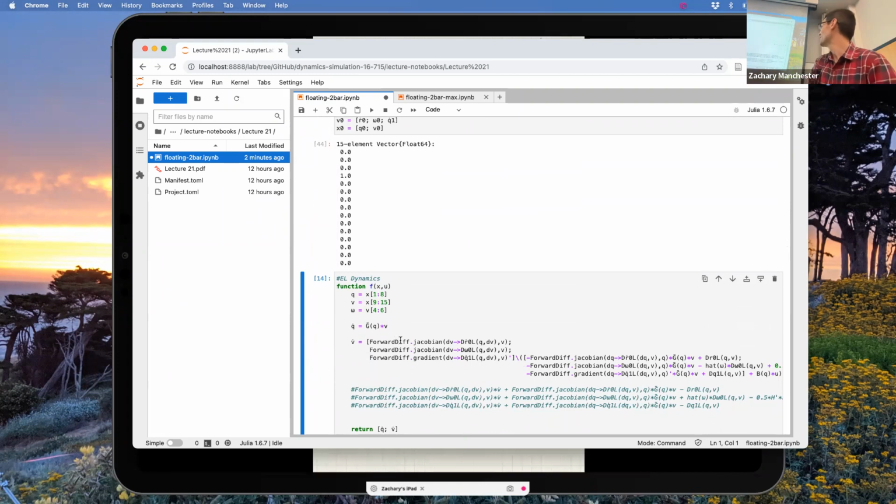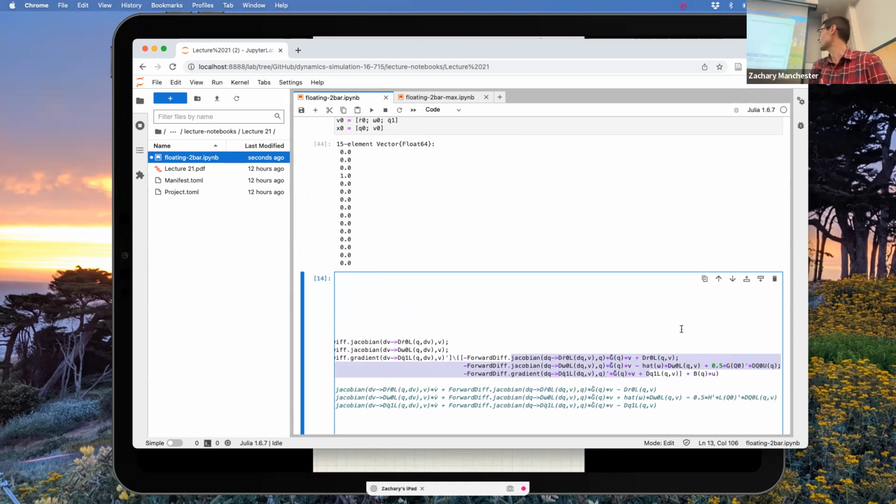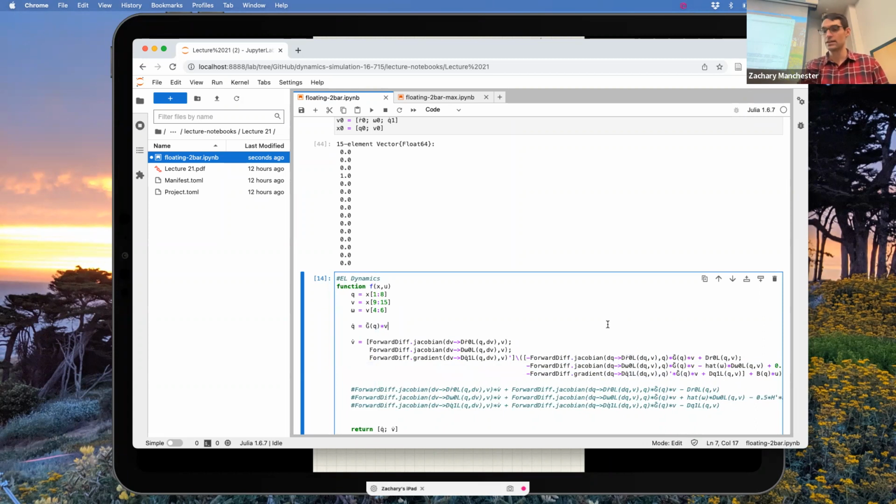So this is messy. But remember, basically what I had was pieces that were separated out for the position, the quaternion, and the omega and stuff. So this thing up here, this is the mass matrix, right? This is the thing I'm inverting. This is the derivative with respect to all the dot things. And then these are basically the potential terms. You see the attitude Jacobian things showing up in here. But these are exactly what we wrote down in class last time. And this is how you actually implement it.